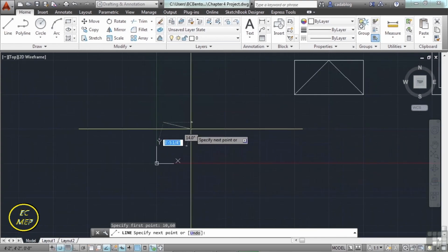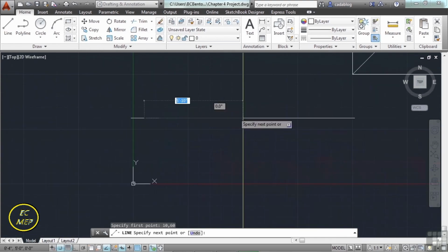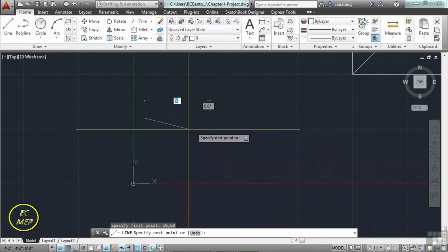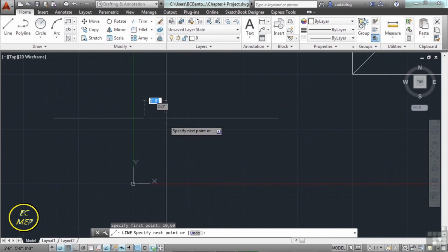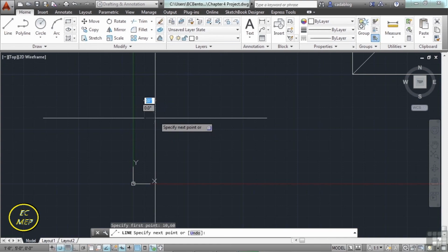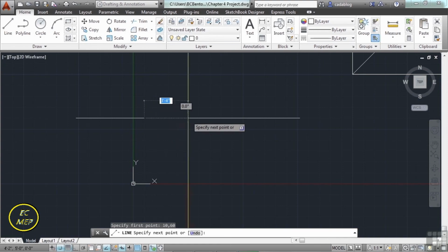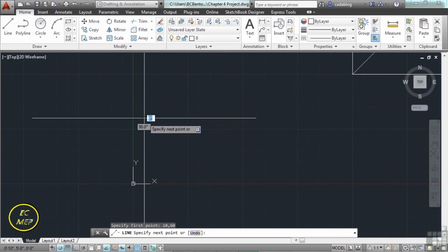So that's great. So if we want to draw a line now that is 50 units long, well, we can snap to 5 different places here on the grid because we have set up our grid to be 10 units long, or we can just do the math on the coordinates. Since we're at x coordinate of 10, we need to go to x coordinate of 60.